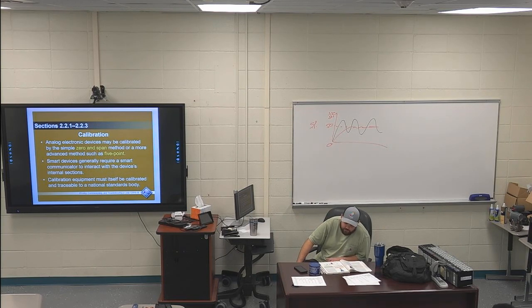The manufacturer creates this table or equation during production. However, it is possible to tweak this stage in the field. Doing so is referred to as adjusting the sensor trim. Adjusting the sensor trim, that's what you want to key in on. That is an online test question.